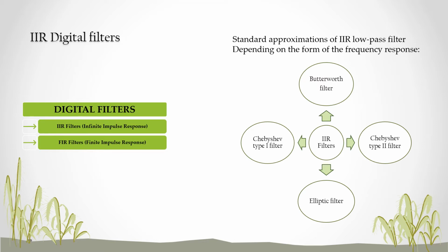A major advantage of the IIR filter over the FIR filter is the ability to approximate the desired shape of the amplitude characteristic well with a relatively low order filter, and that's a desirable quality. However, the IIR filter, unlike the FIR filter, cannot have a completely linear phase characteristic, which may be a disadvantage